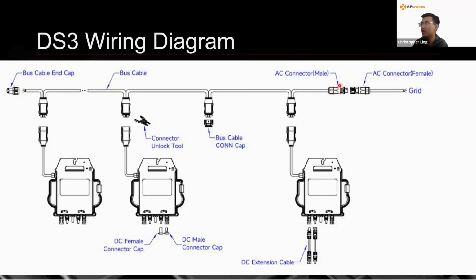And then on the other side, you have a connector over here where you can either use an AC connector that you can purchase from us, which is a screw terminated connector, or you can use a simple J box just to terminate the wires. That's what we generally see in the field, and that's basically how you do the AC wiring.